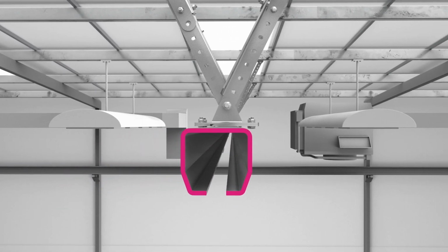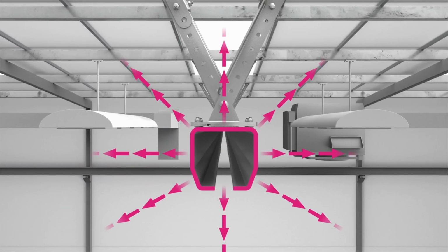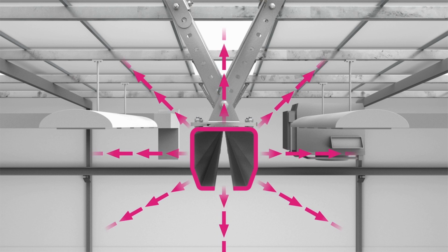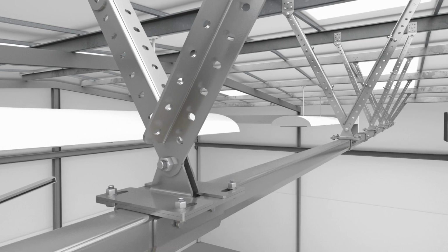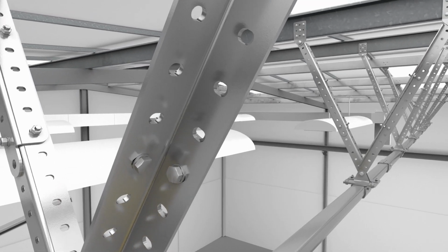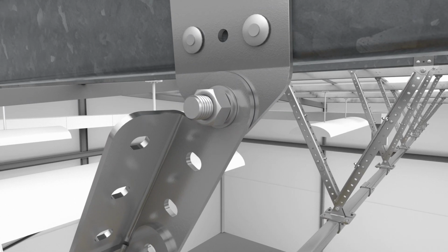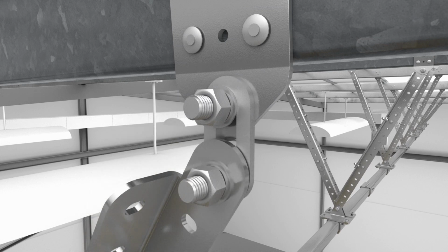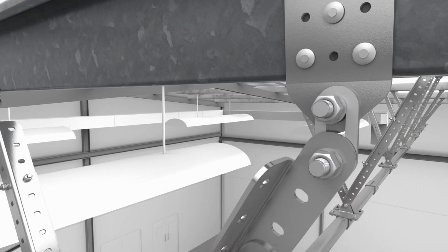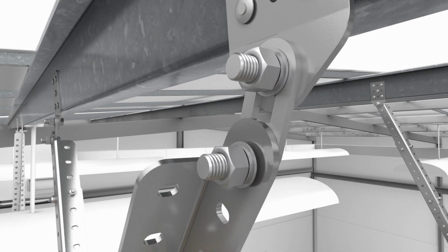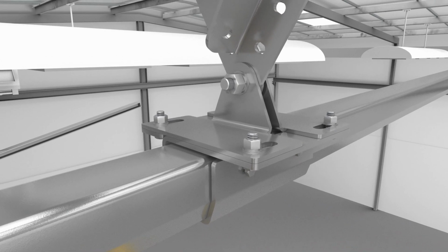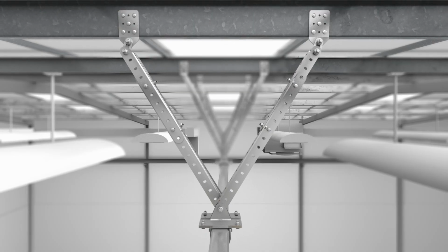In some situations, it may be necessary to shift the clamshell position either horizontally, vertically, or multi-directional to ensure the rigid rail is level and running true to its proposed position. In addition to any coarse adjustment achieved by on-site amendment of the hanger link arm length, the slotted adjustment washer can be incorporated into both purlin brackets at the interface with the hanger link arms. Installed at both purlin brackets, the slotted adjustment washer allows for significant multi-directional movement of the clamshell assembly and subsequent rigid rail alignment.